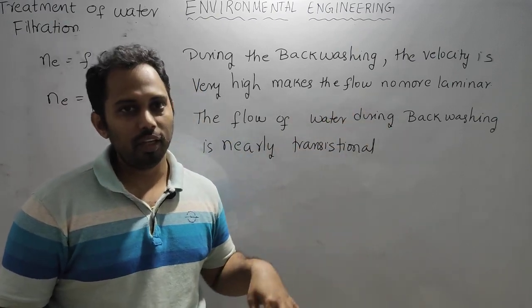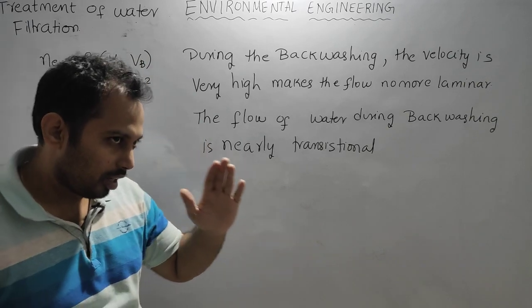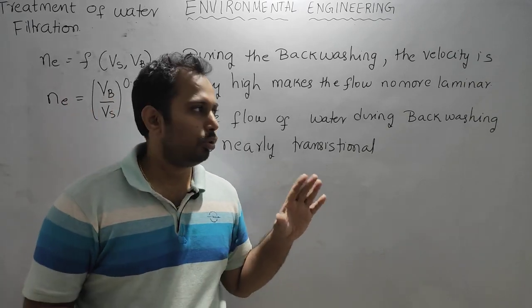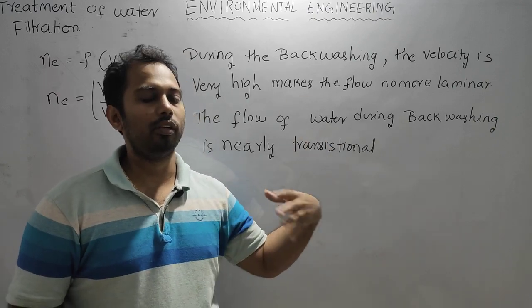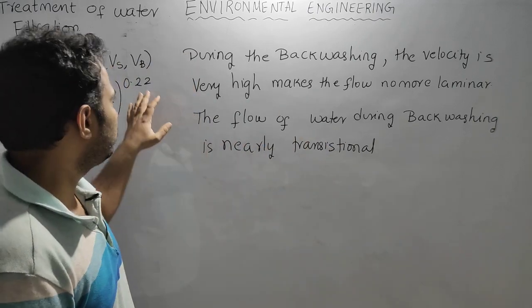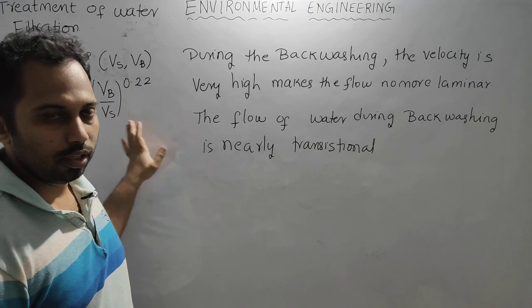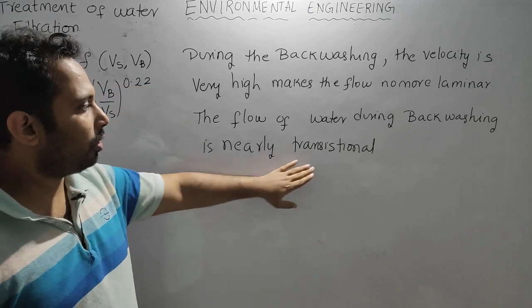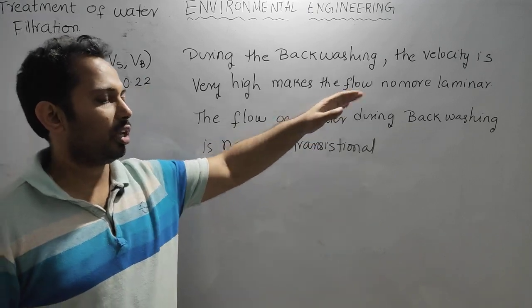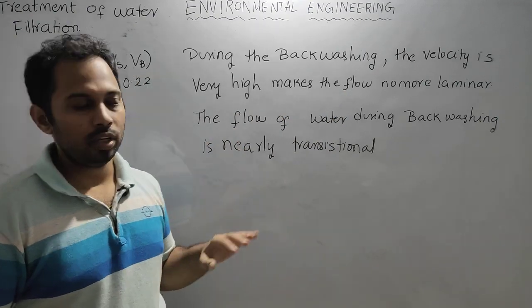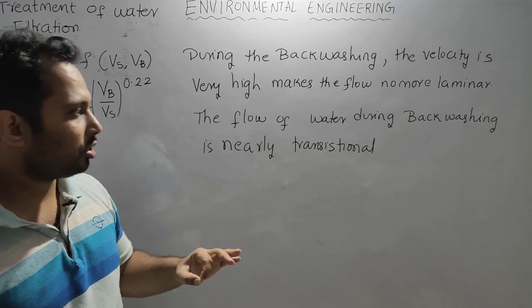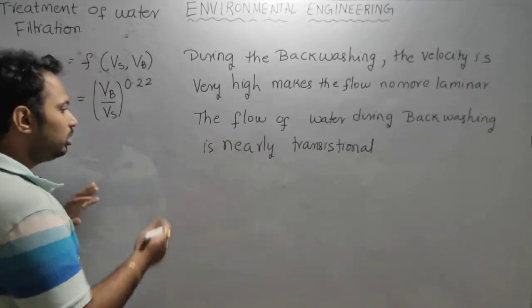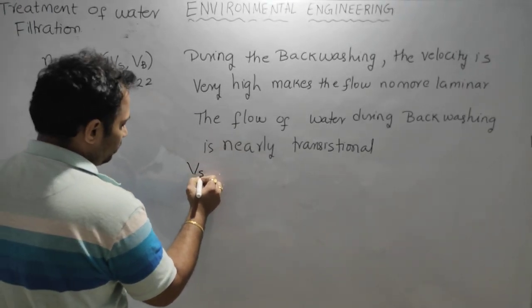But generally, as far as the GATE examination is concerned, we take the settling velocity as in laminar flow only. That means here also we use the same formula of Stokes law. Stokes law is not applicable in transitional flows; it is applicable only for laminar flow. But during backwashing there will be transitional flow, so during transitional flow the settling velocity is defined like this.